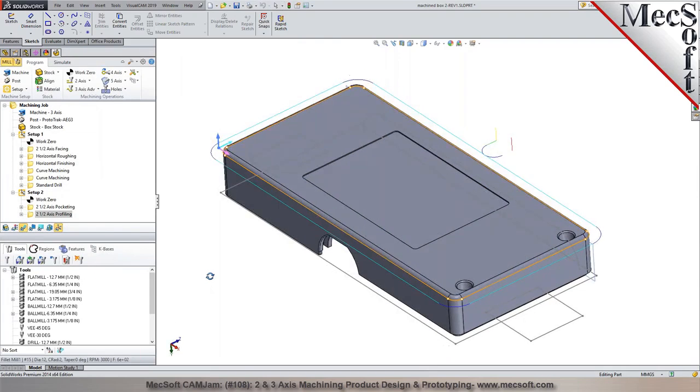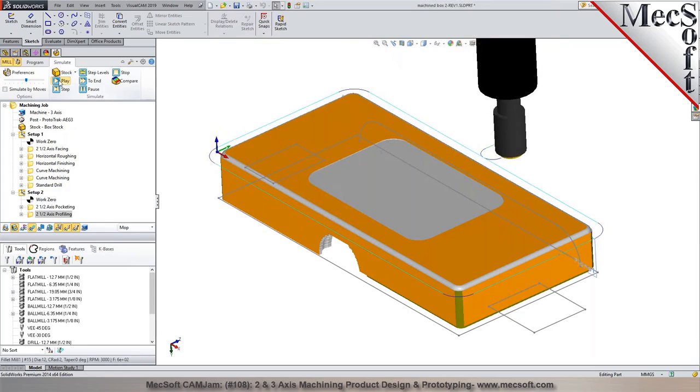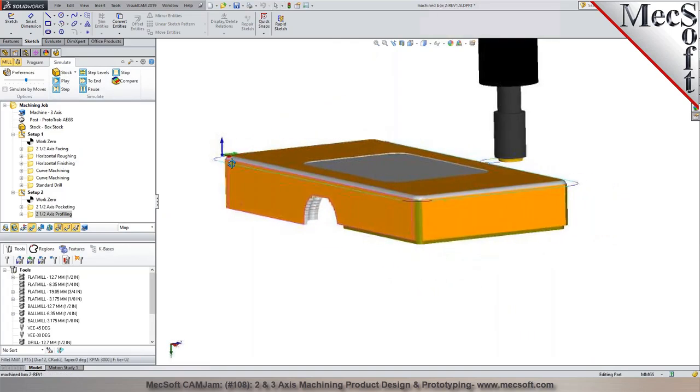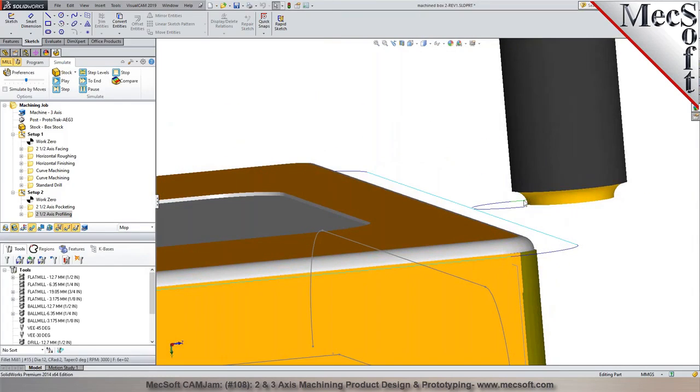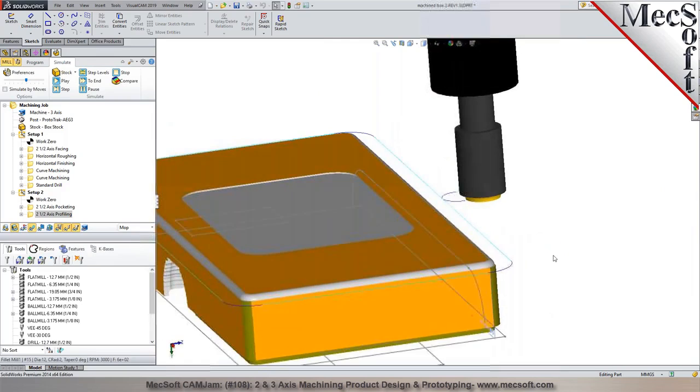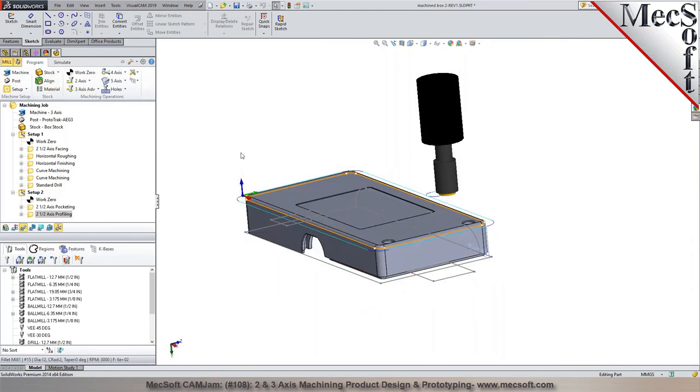So that'll go ahead and take. It automatically finds out your levels for that. So you can see in one pass, I was able to machine the fillet with a tool that matches the radius of the fillet. Corner round tool. Nice. So the Pro gives you the ability to program from multiple setups.